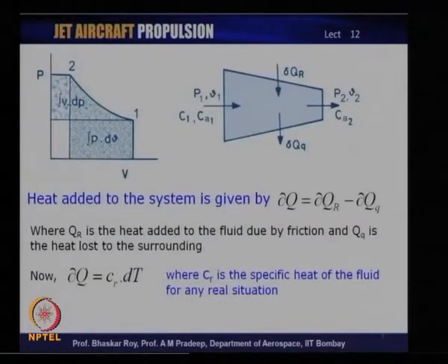If you look at the PV diagram, and on the side you have a system in which the flow is coming in with P1, V1, and let us say a velocity C1, in which case it could be an actual velocity CA1 coming straight into, let us say, a ducting system. And then we say that this process now has a possible heat addition or rejection.